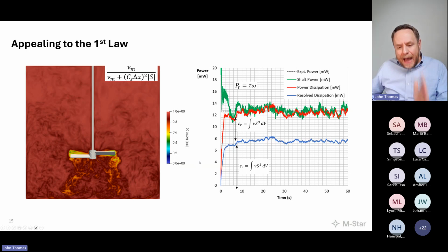So what would we expect would happen as I increase my resolution? Well, as I increase my resolution, I'm going to be seeing more and more of that turbulent energy explicitly, right? I'm going to be relying less and less on this filter. So again, this delta X, as my resolution gets finer and finer, that should get closer to 0, right? And the flow field doesn't change. You're not going to see strong changes in strain. But as this delta X gets smaller and smaller, this is going to go to unity everywhere, implying I'm approaching and recovering DNS.